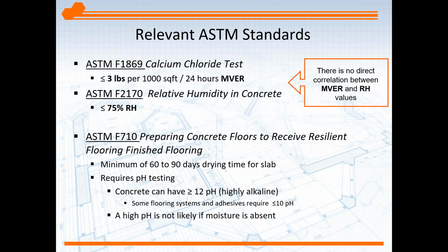As far as relevant standards, there's a standard for the 2 common tests, calcium chloride test and relative humidity test. It's important to note that these measure moisture in different ways and at different times, and you can't correlate one versus the other, meaning if you know the MVER, moisture vapor emission rate, you can't extrapolate that to a percent RH, or if you know the RH, you can't extrapolate that out to the pounds of moisture.